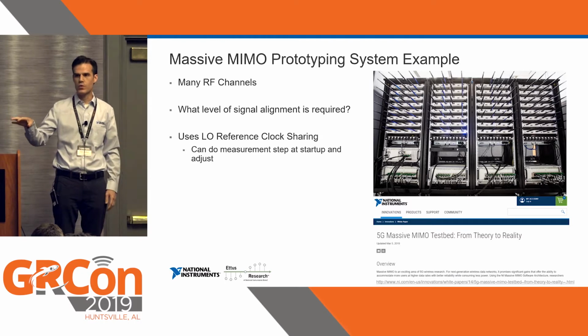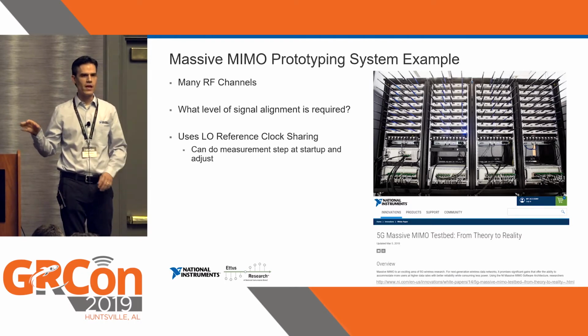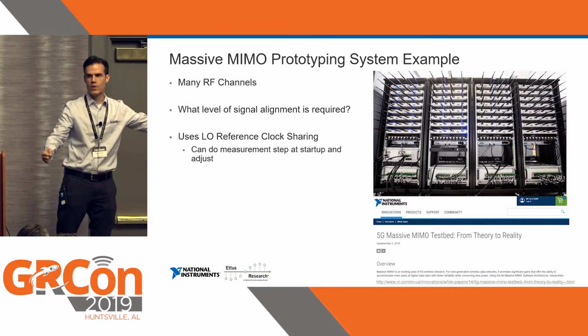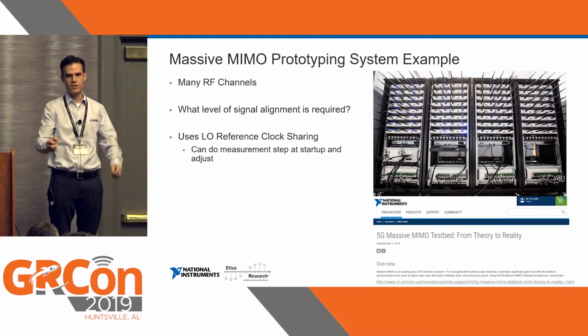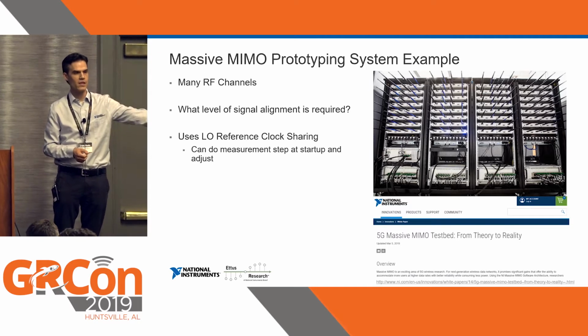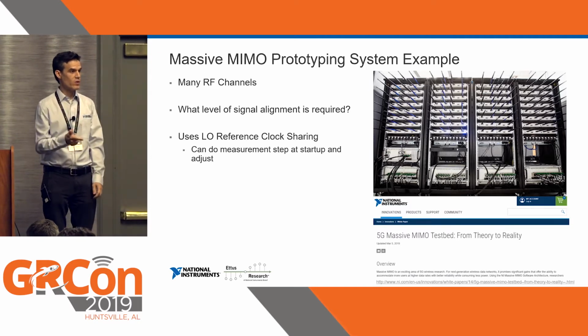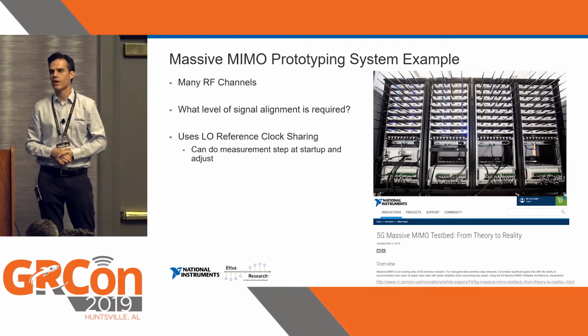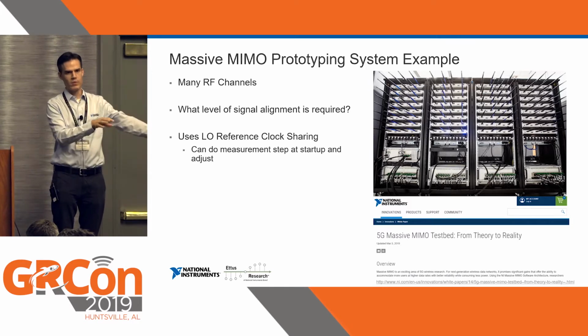There's actually a cool YouTube video you can watch where they have this system in one room, and in the next room they have some microphone stands set up to represent people, and they have an omnidirectional antenna on each of those microphone stands. At the same time and on the same frequencies, each of those antennas was receiving a unique stream of data. Right? So that's spatial multiplexing.